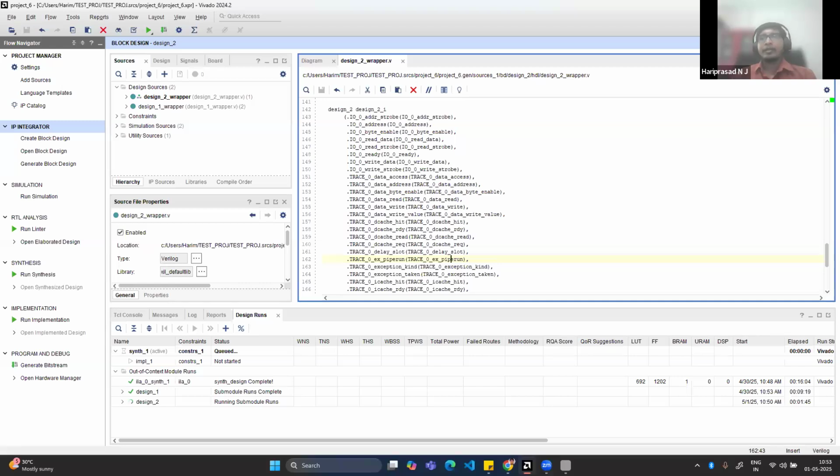Because when you use a lookup table, as I told you, it is not going to utilize the dedicated clock path. Another disadvantage is that you don't know the logical delays, which impacts your duty cycle and all. So you will not get a stable clock. So you have to go for MMCM.